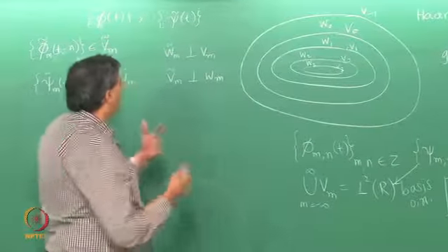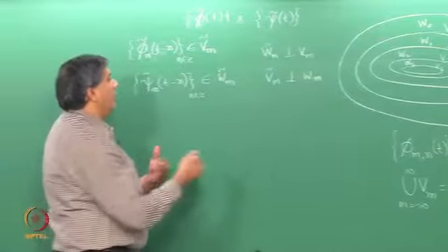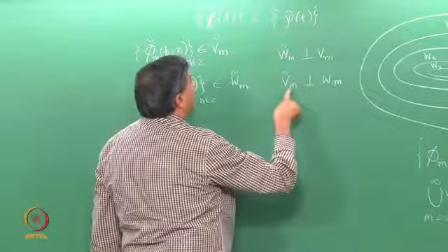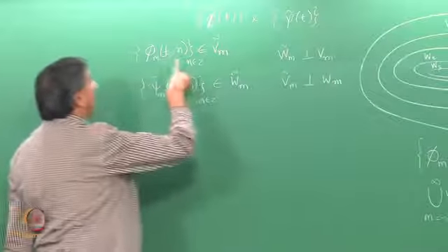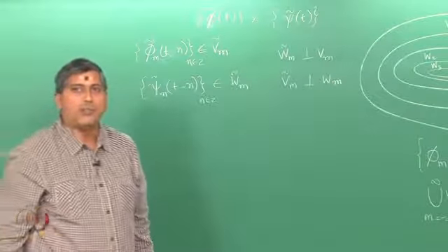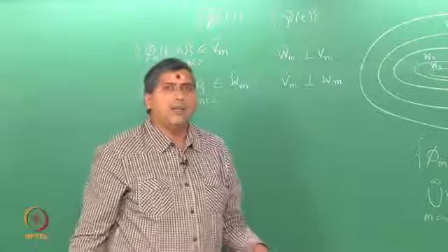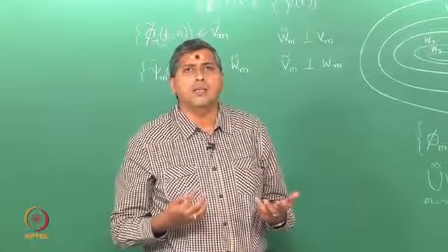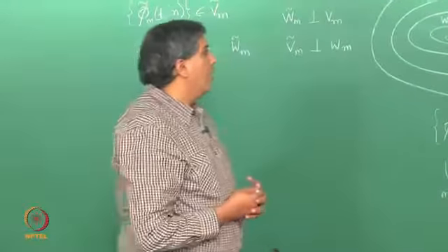In this here it is a biorthogonal. So, you see that Wm is not perpendicular to Vm, but it is perpendicular to the approximation space generated by the synthesis wavelet functions. Now, on the face of it, it sounds a bit weird. What does this mean?